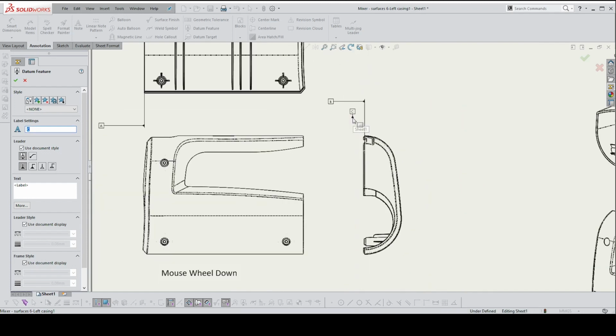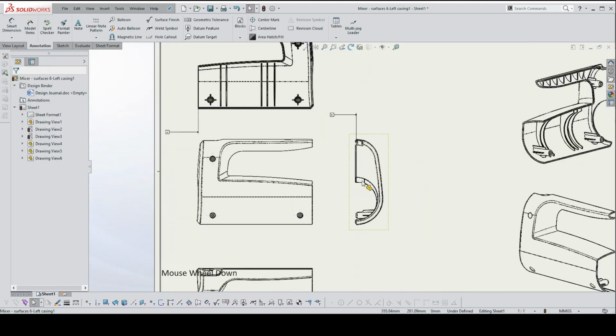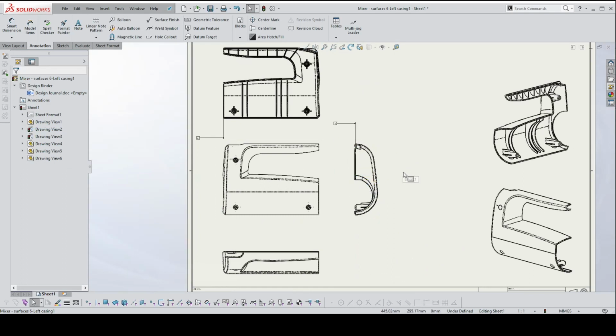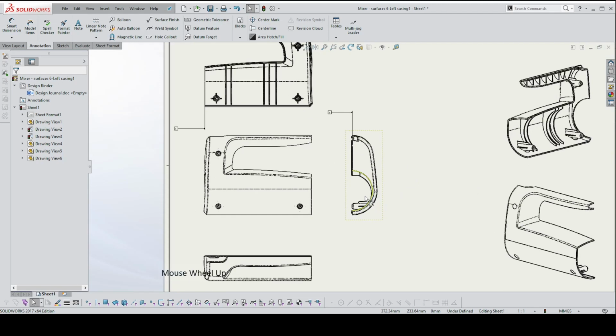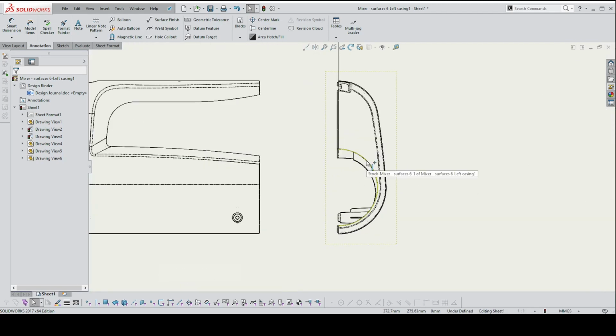Place that out there. And then the third datum, as you can see, we've got no other straight lines or starting points. The third datum is going to have to be either this cutout here, because that's in the cutout it's an actual circle, or this recess in the rib which holds the motor. Now that's the more natural one because the motor also forms a natural kind of locating feature. It's the starting point or the origin of the entire design. So I'm going to select that line. There are 2 reasons for it. One is because that makes sense. Second, because this is not actually a circle.